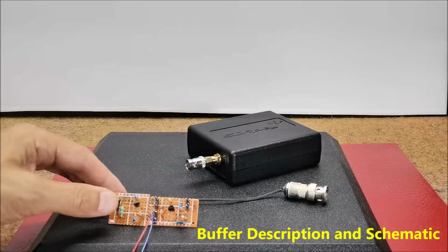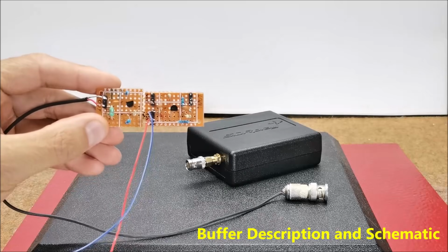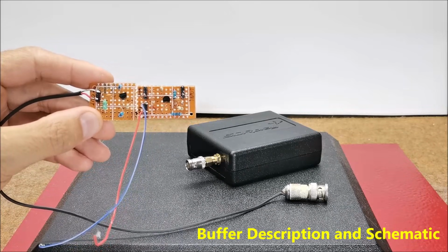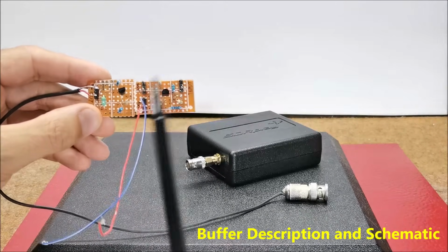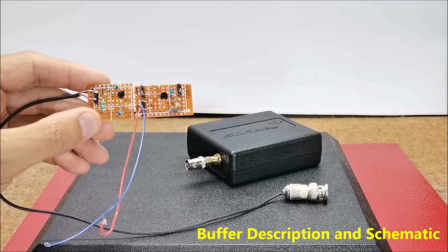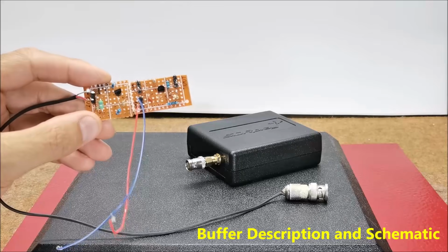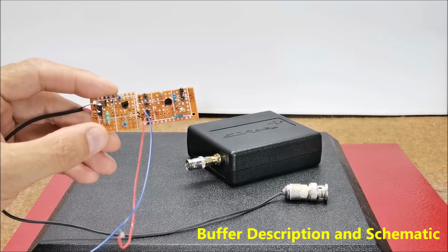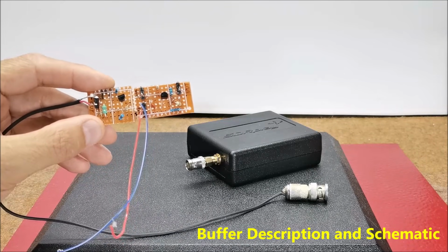And now a few words about the buffer board. Tube radios often have very high impedance signals. They are meant to drive loads into the hundreds of kilohms or even into the megohms. If you take a regular amplifier designed for a 50 ohm input impedance, you'll suck the signal right out of your radio and there will be nothing. You'll completely load down the receiver.